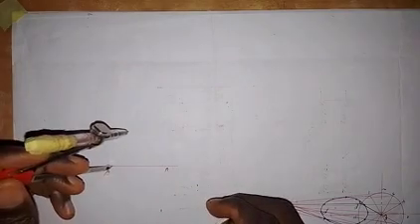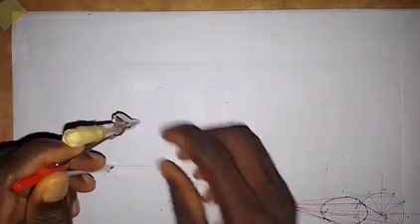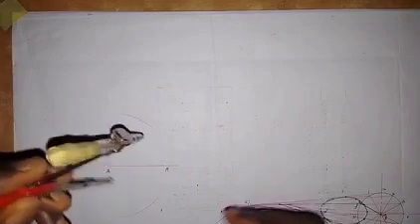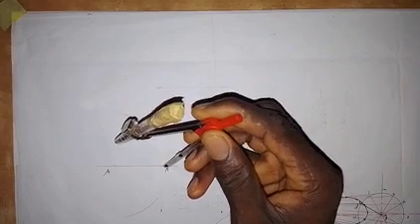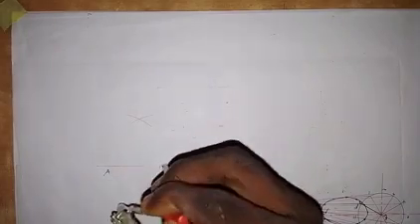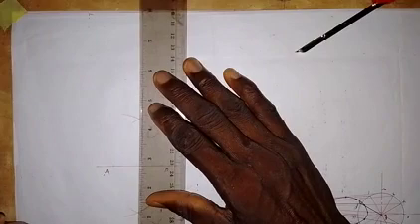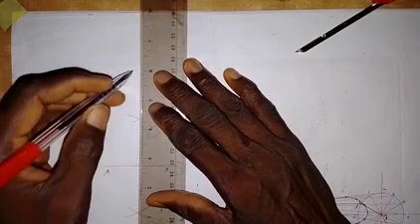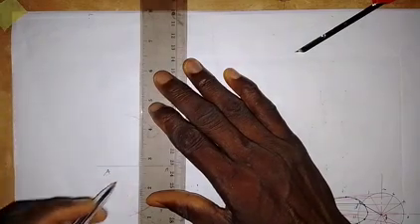The next thing I'm going to do is divide this line AB into two equal parts. That means I'm bisecting it. So I will draw an arc up here and then down here, putting the compass at point B. Then I will draw a line. I don't need to draw it through both points of intersection of the arcs, I just need it up here to bisect line AB. So I have it like this.